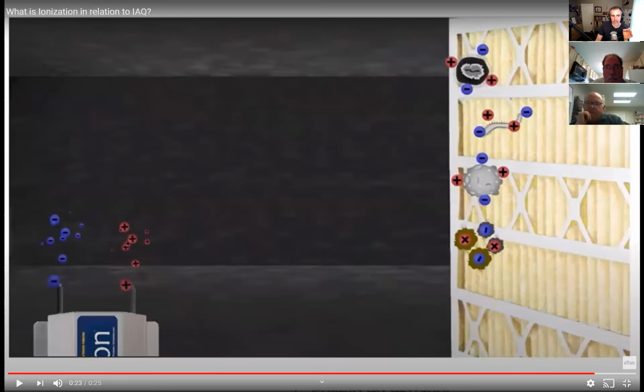And the biggest impact here is that this purple sphere is a great representation, right? So at the very center, picture that being the tip of the UVC bulb. As you move outward from the body of the bulb or the body of the lamp, you are decreasing in intensity. So obviously the closer a lamp is mounted to a coil surface, the more potent and strong it is, because you're hammering it with those levels of microwatts.